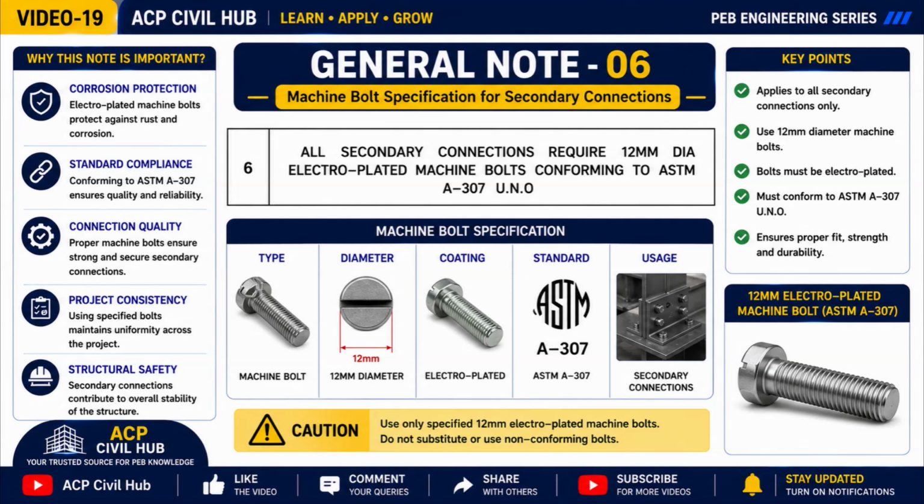Secondary connections include components such as purlins, girts, sag rods, bracing accessories, and other non-primary structural members where this specification is applicable. The electroplated coating provides protection against corrosion, while the ASTM A307 standard ensures the required mechanical properties for these connections. Using the correct bolt diameter, coating, and standard helps maintain proper fit-up, reliable fastening, and long-term durability of the structure.